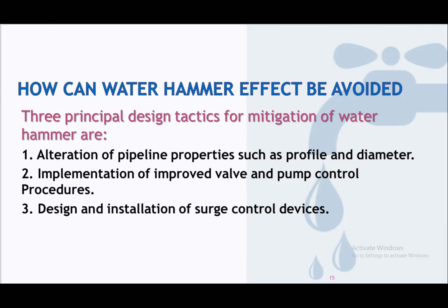If you're increasing the diameter uncontrollably, this will lead to increasing the weight of the water column we were talking about earlier, and that will, of course, increase the pressures. So you have just to try and control the diameter in an estimated value, not just putting as high a value as you want and assuming that will make you safe against water hammer. No, that won't make you safe, okay?